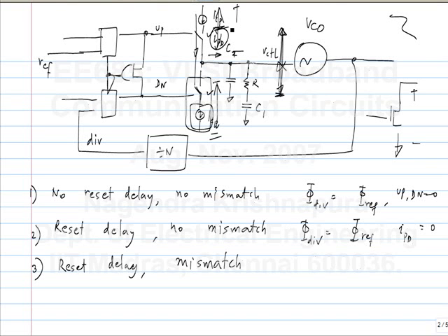If the reference frequency? No, in this case there is no effect, right? Because it's sensitive only to the edges. So it's sensitive, let's say, to the positive edges of the two. So it doesn't matter. That's why we came to this kind of phase detector also. So the duty cycle output of this doesn't matter.